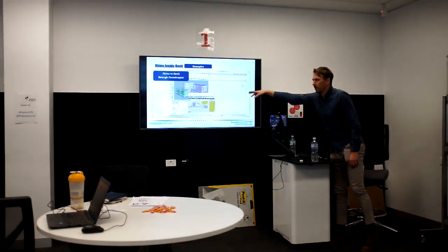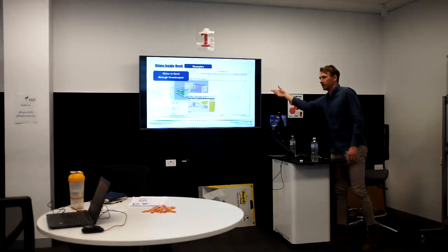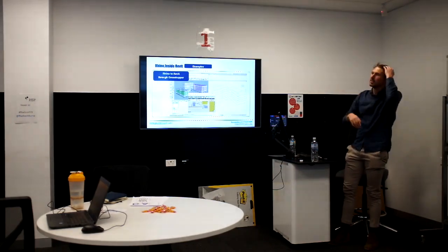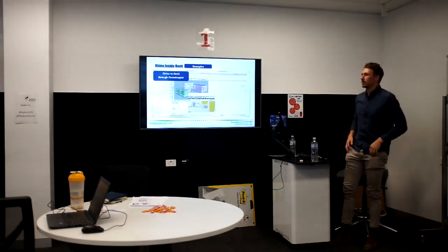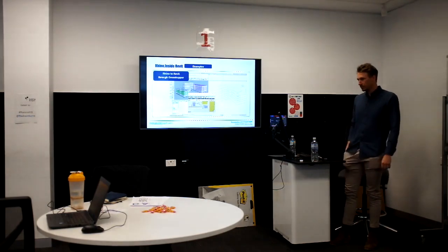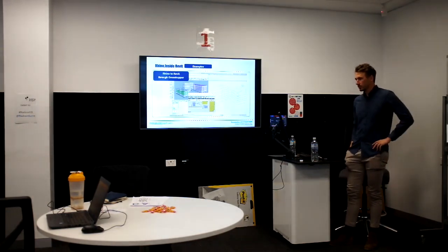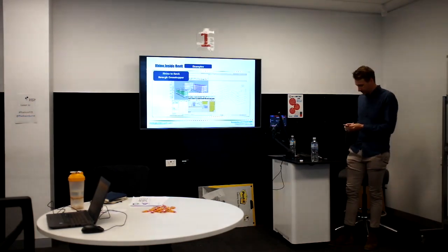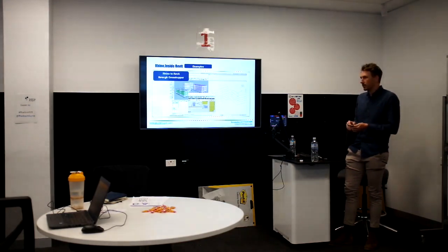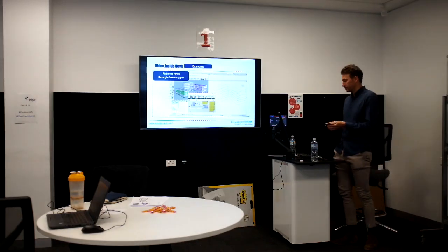If you close that down, I'm not sure, you were talking about that issue before, weren't you? If you close Grasshopper down and then redo it, it sort of updates the... Yeah, the live link will be broken. The GUID, if you have it all open, it's fine. It updates dynamically. But if you close Revit, or I think Rhino and Grasshopper as well, the GUIDs aren't maintained, so it creates a new geometry over the top. That's my experience with it.